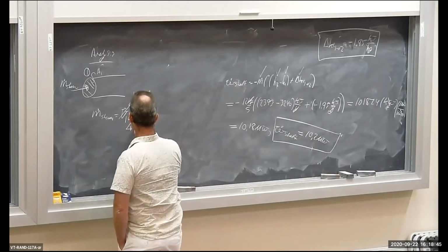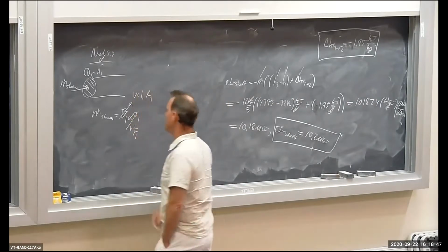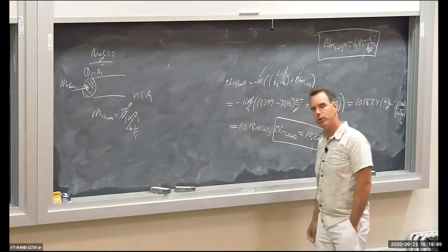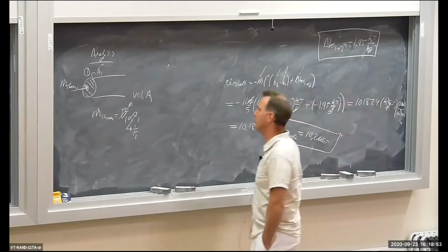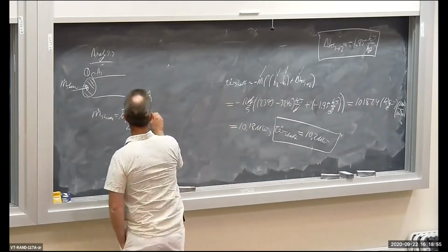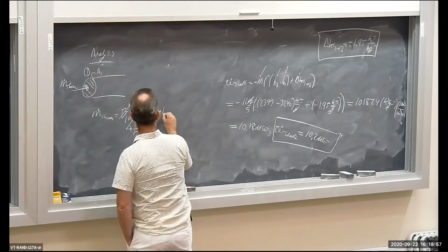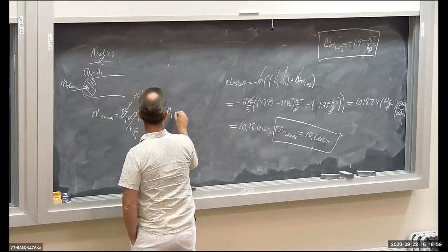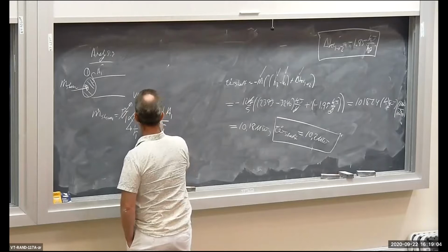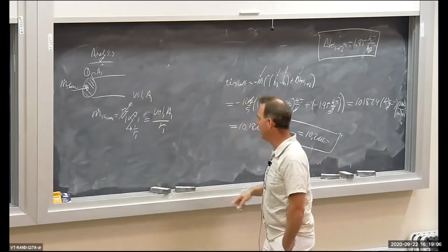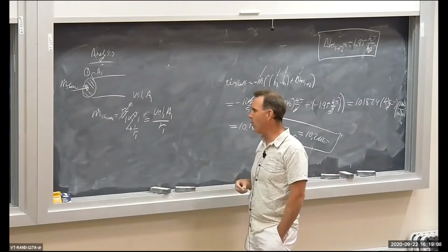So this guy is 1 over specific volume at the inlet. Tables don't give you density, they give you specific volume. That's why I'm converting density into specific volume. So I have velocity 1, area 1, over specific volume at the inlet. Okay? Now the inlet area is what I want, A1.